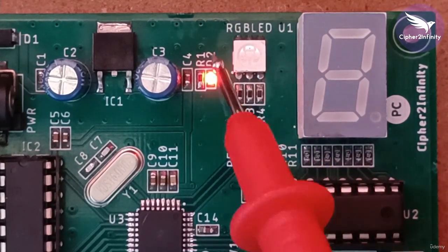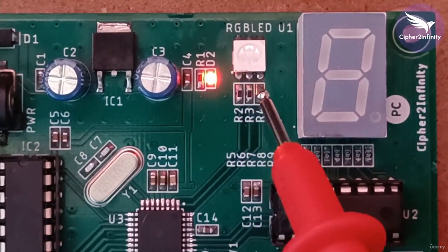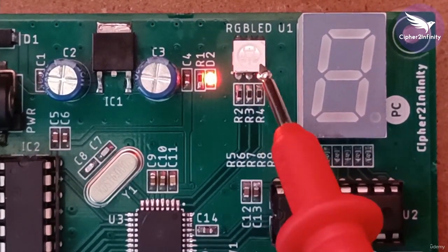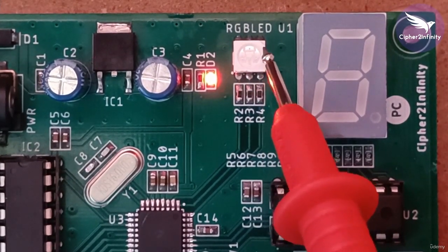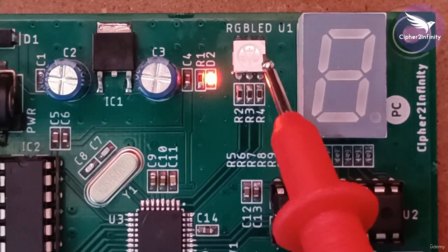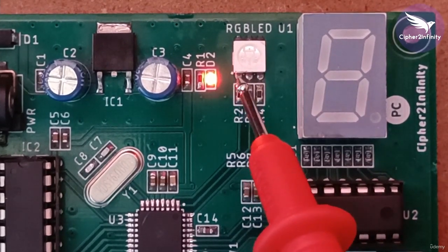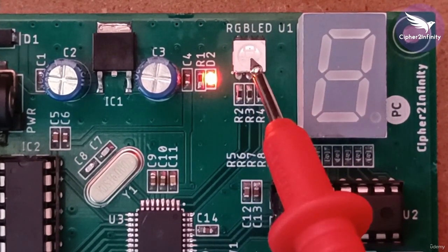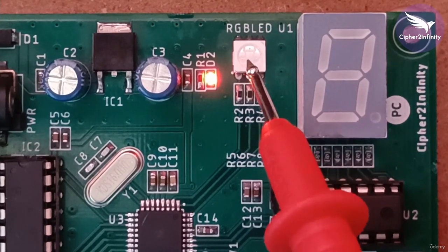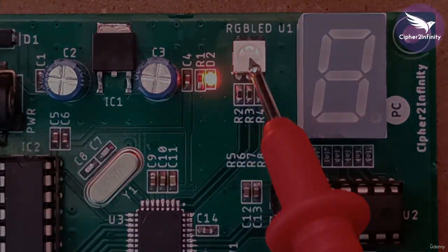Okay, so if you soldered the RGB LED in the wrong polarity, then it's obvious that the LED is not going to switch on. So whenever you solder the RGB LED, first of all you have to make sure that the polarity of the RGB LED is correct. So this is the notch of the RGB LED, and this is going to be pin number 1 of the RGB LED. So accordingly you have to solder this particular LED on the PCB in a correct manner. Okay, so I hope that this particular point is now clear.